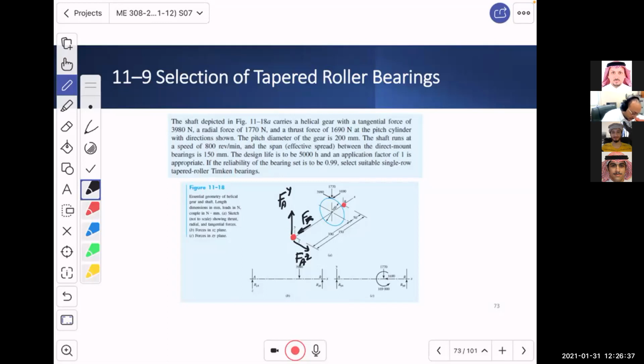Now, what do we need to do? As usual, we need to go and sum up the resultant over there. And once we know the resultant, that's it. Do you remember what we should do? We multiply by 0.47, multiply by the resultant, divided by K. And then we find the induced thrust at A. We do the same at B. And then we analyze: is the sum of the thrust the same, is it different, and so on. That's the process. Yes? K will be 1.5? We will start with 1.5, yeah. Don't worry, this is what we are going to solve.